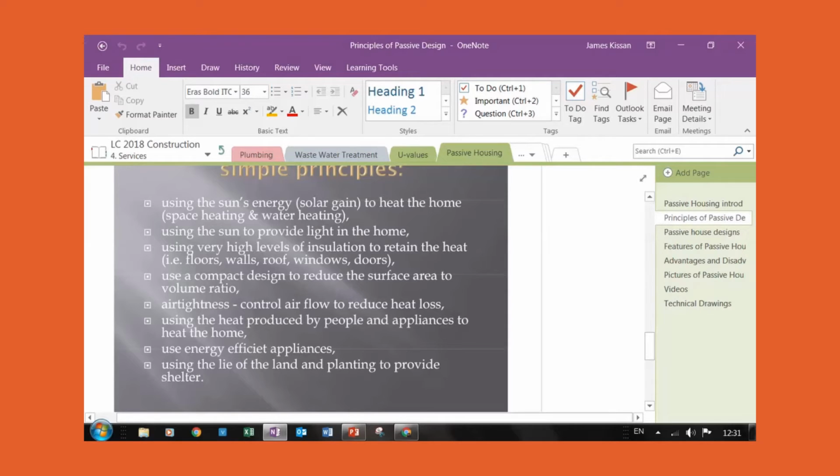So the space between the wall and the window will always be taped together before it's plastered over to create this airtight seal. And it's all about creating an airtight house so that no heat escapes. If you have air escaping out of the house through gaps in the building fabric, that means you've also got heat that's traveling out with that air. And also, if air is able to escape out, you have cold air able to escape in.